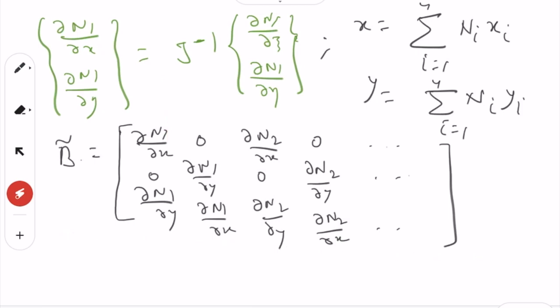In other words, you know the way we calculated k11, for example: we took the first column from here, multiplied by the D, and found that k11 was this squared plus (1 minus nu) over 2 times this squared, which was being integrated.